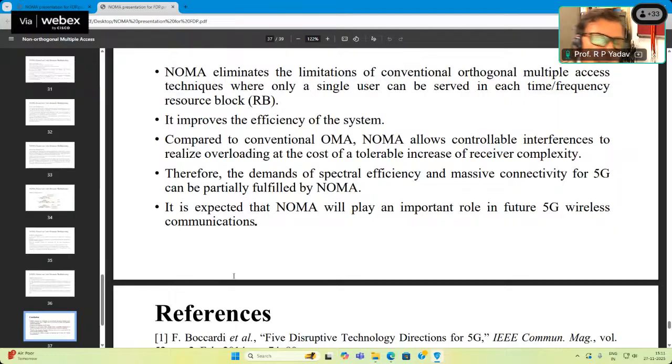Now, extend this logic to high-frequency instruments, like in the case of 5G communication. The 5G communication spectrum, right now, is working in the sub-6 gigahertz band. You have already had some lectures on that, corresponding to some 3.6 gigahertz and below. And then you have particular bands allocated between 10 to 20 gigahertz also, and 20 to 30 gigahertz, up to 50, 60 gigahertz. That bandwidth allocation has been made for 5G communication.